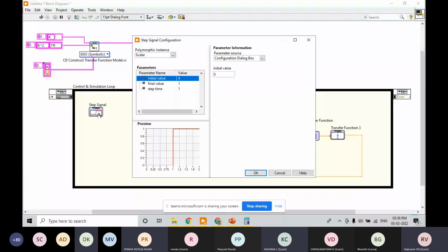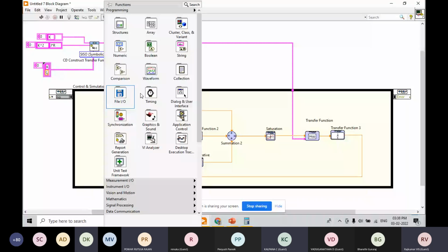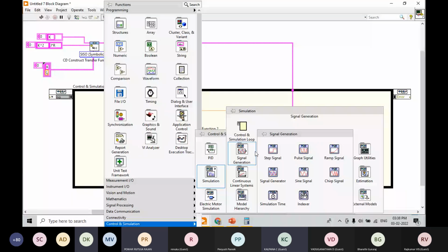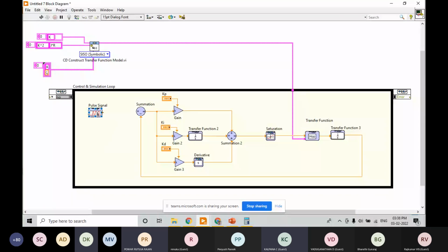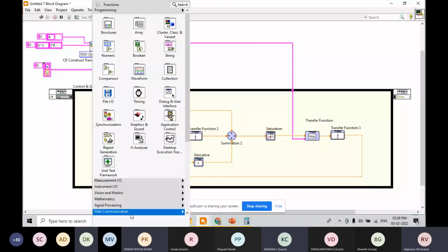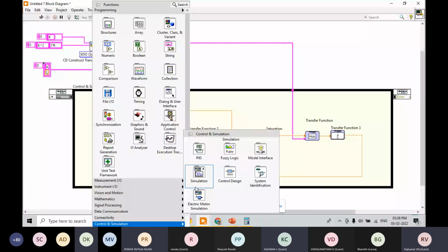Or you just want to keep changing the values. Instead of giving only one step, perhaps you want to keep on testing the steps. So you can try giving pulsing, so positive to negative, you can keep on going. That also you can give. The DC motor is capable of rotating in both directions, so let me use both positive and negative amplitude.